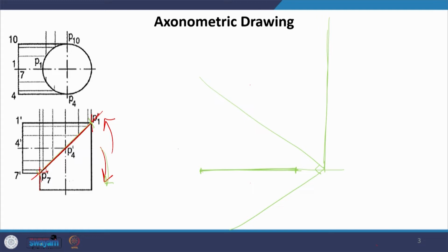Okay. And now I will draw the rest of the plan like this. So, this is the plan that I am talking about. Now, I have 12 different points here. So, these are the 12 different points and I have their heights here, which is the same height as the 12 points on this circle, which is now here. So, what I will do, I will just take the intersection first. There were these 12 points which we can get. This is P4, so approximately like this, and now we have to give them the heights.